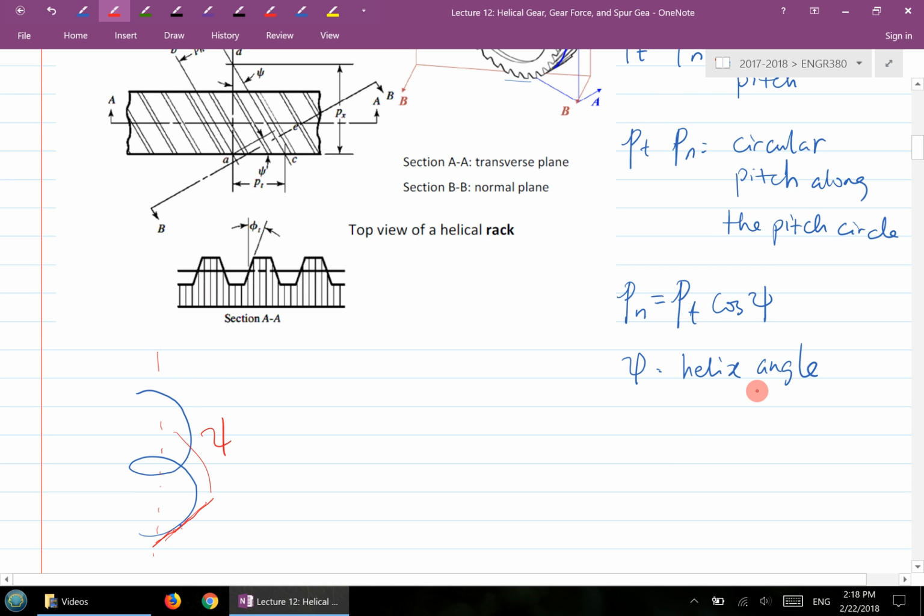For a helical gear, you can specify what helix angle you want. The larger the angle is, the smoother the rotation is going to be. The manufacturer usually will dictate the amount of the helix angle; it's not arbitrarily given though.